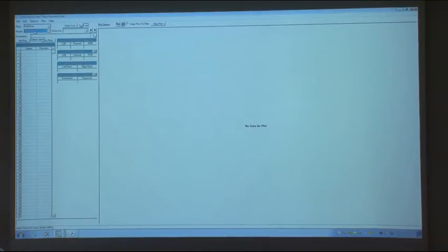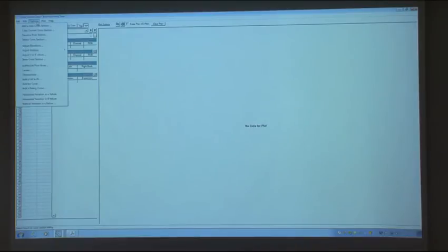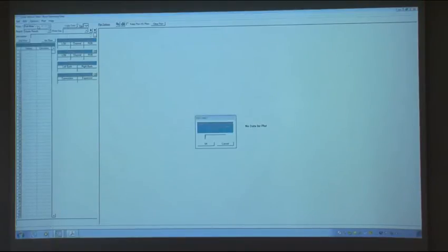And then you can go to the options, okay? Because if you don't select the river and the reach first, you go to the options and you may enter the cross-section data in the wrong river and the wrong reach, okay? So now you have to go to the options button. The first one available to you is add a new cross-section. So let's click on that.